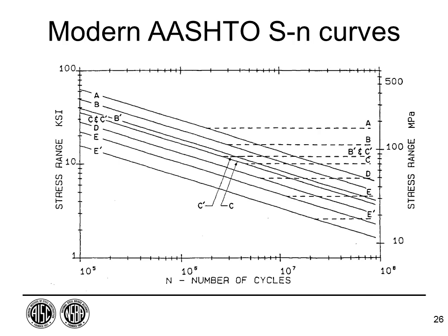And so there's all of these different details. I'd use the detail category and detail constant term. And really, this is the same curve, right? It's stress range, number of cycles, except now we see a whole series of curves. But they're basically the same. I have a sloping portion, and I have a constant amplitude portion.